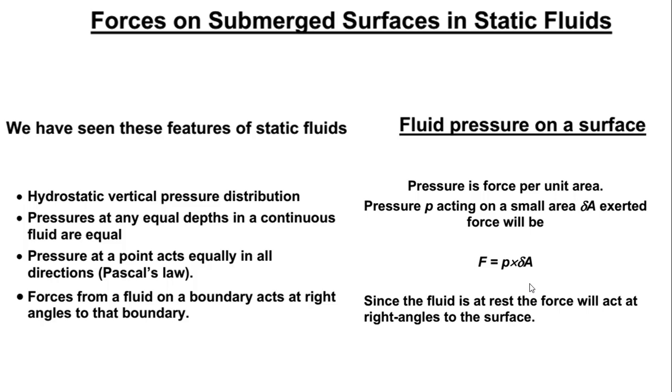So far we've seen that whatever force acts on static fluids is supposed to be acting perpendicular to the surface, at right angle to the boundary. The other thing we have learned, when you look at Pascal's law, is that pressure at any point acts equally in all directions. This is only true for a continuous fluid. If you remember last time, we talked about forces acting equally in all directions for a fluid that is continuous.